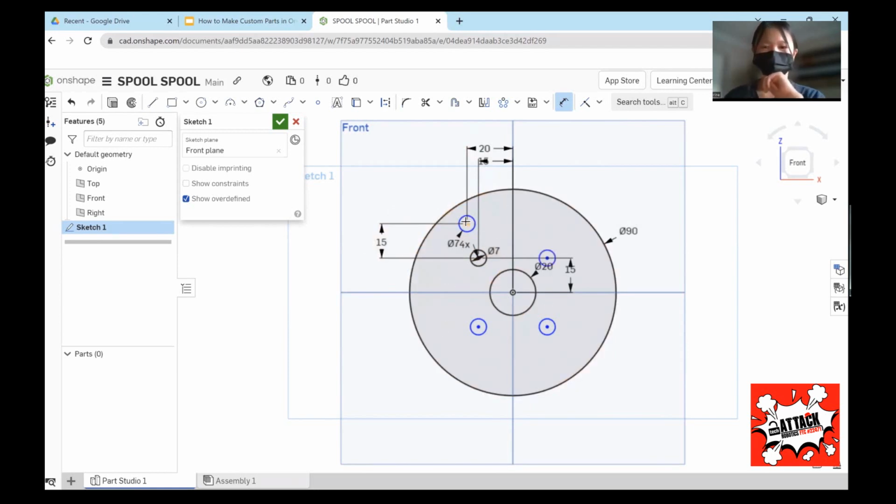So after you got another circle that looks to be in the right place, get off the dimension tool by pressing escape, and go back to circular pattern. It should have saved from last time you used it. Press that to make another linear pattern, and press the circle you also just dimensioned, and it should go back to 3.